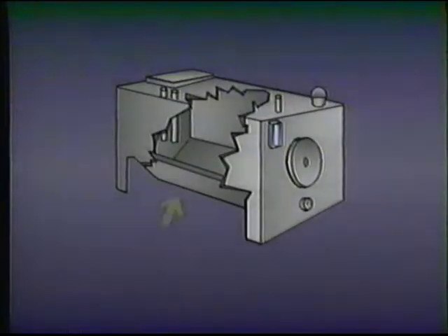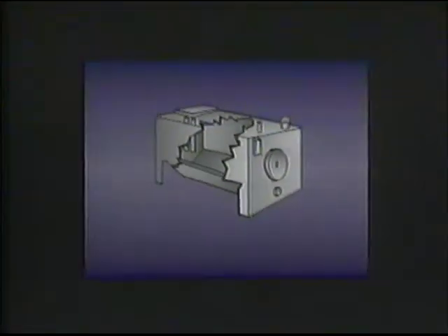The reservoir's dished bottom collects the dirt, and an end cover permits occasional cleanout. A drain allows sampling of the fluid. A gauge indicates the fluid level. A filler cap includes a built-in breather to let air escape. A sturdy plate provides a place for mounting the pump and motor.